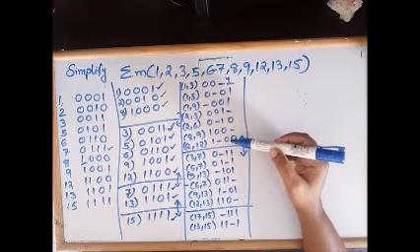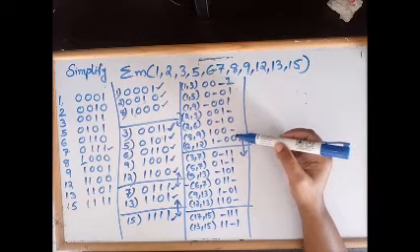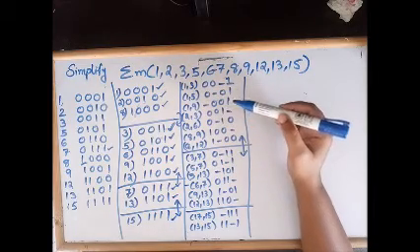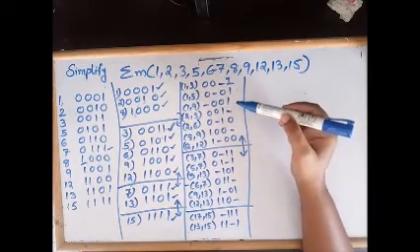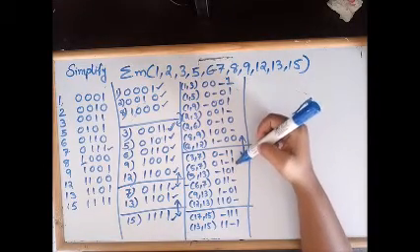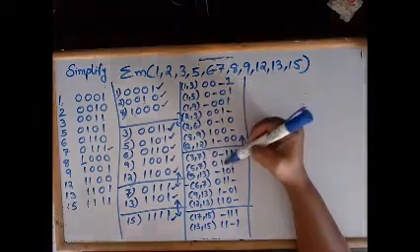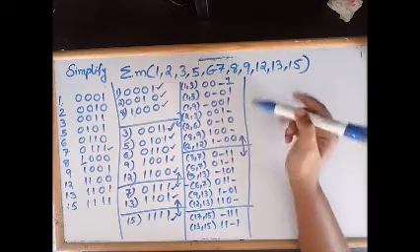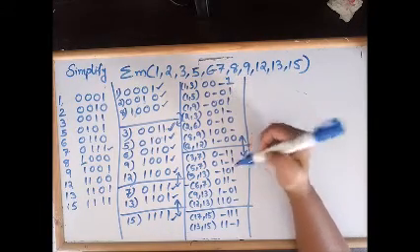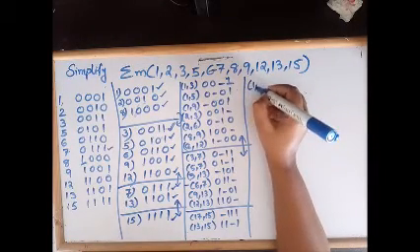So when you compare these two, what about the bit difference? One bit change, second bit change, so more than one bit difference, so we cannot combine. Then again check 1,3 and 5,7. The LSB is the same, the next bit is the same, and there is one difference, and the last bit is the same, so we can combine 1,3 and 5,7. So I am combining these two. This will generate a new group.